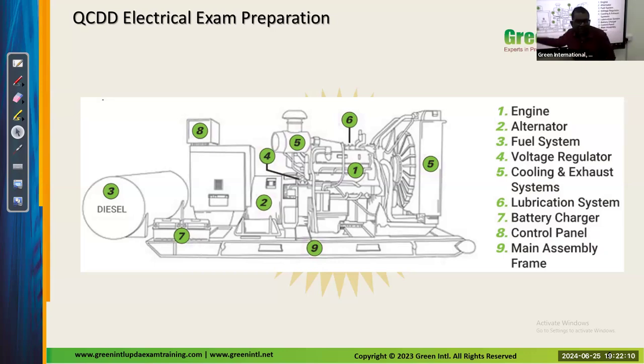Suppose the fuel is empty, what will happen? We need to ensure that, so we have alarm systems. All of these put together we call the control panel. In the standard, we have one chapter on alarms and control panels. Right now we are using electrical power, and unfortunately the power fails, so we need to go for the backup, that is, the standby system. There is a time delay between the prime power failure and switching on the standby.